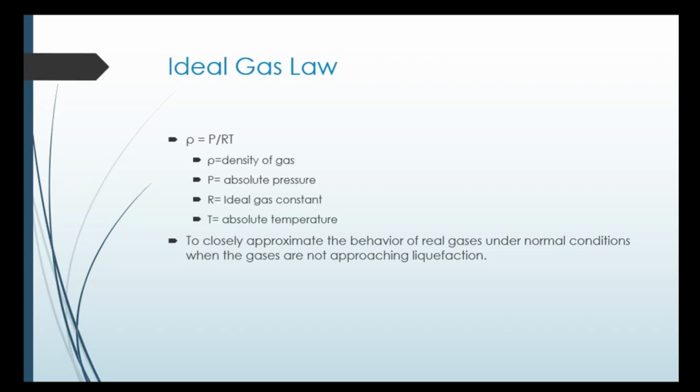You start measuring from, if I draw a line from here, in general, you are measuring pressure from this reference. This is your atmosphere. The line is your atmosphere, and it is always at 14.7 psi. If you add 14.7 into gauge pressure, that would be your absolute pressure, because this height is from 0 pressure.